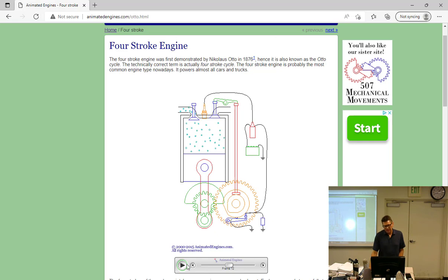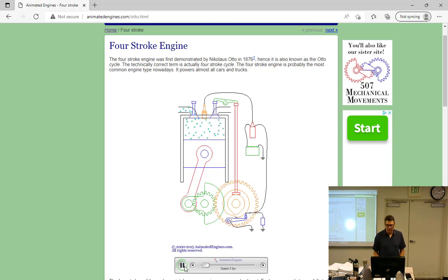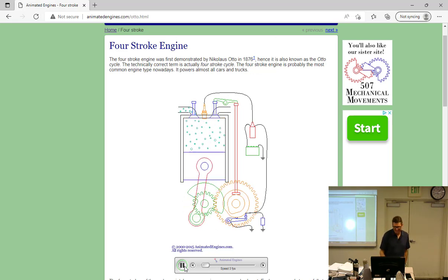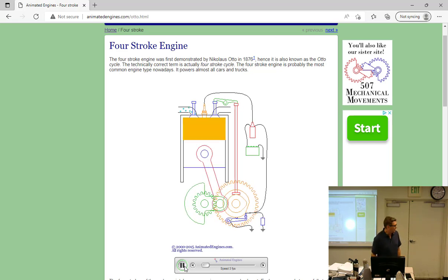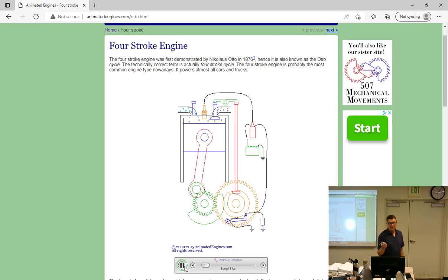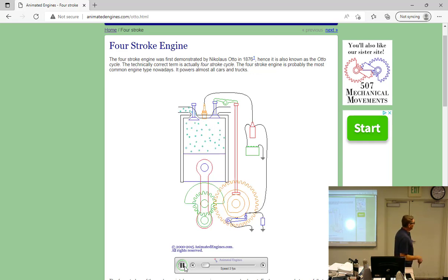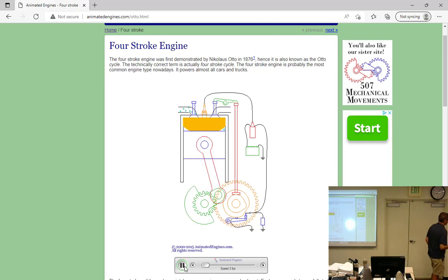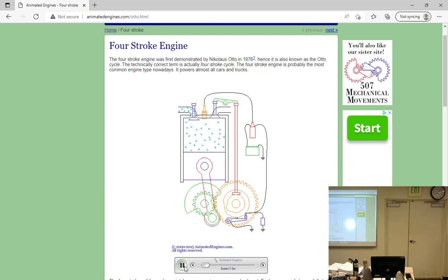And I always say the crankshaft, that's this red one right here, the crankshaft is the brute part, that's the muscles of the engine, but the camshaft is the brains of the engine. And the reason why is because the crankshaft, all it knows is up, down. What's a cam? I'm going to get to that. So I'm glad you asked. So the crankshaft, everybody got what a crankshaft is? Crankshaft is the muscles of the engine. It knows up and down. So it goes up and down. It turns reciprocating, means up and down motion, into rotary motion.